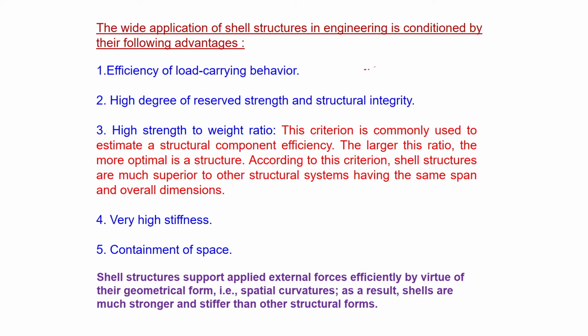Very famous example, if this is a thin sheet and this is a corrugated sheet, when you have structures, aluminum, steel for roofing purpose. Basically this curvature makes them more stiff, even though the thickness remains the same. For a roof or a structure, these corrugated sheets are mostly preferred compared to flat sheets, which cannot take more load. Just because of the curvature they have more load carrying capacity.